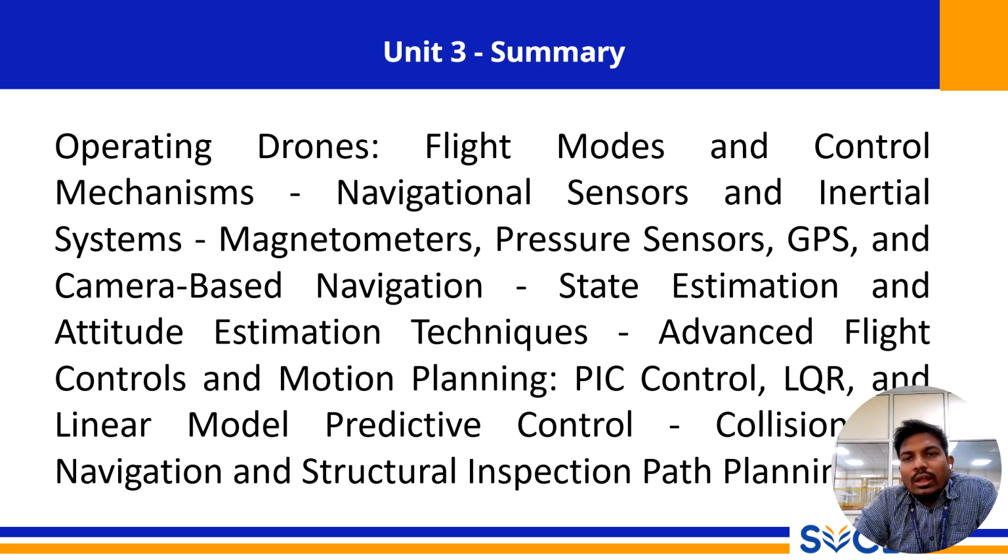Techniques like the linear quadratic regulator, or LQR, allow an engineer to design an optimal controller by balancing control effort against performance, while linear model predictive control, or MPC, can plan optimal control inputs over a future time horizon, allowing it to handle complex constraints more efficiently.